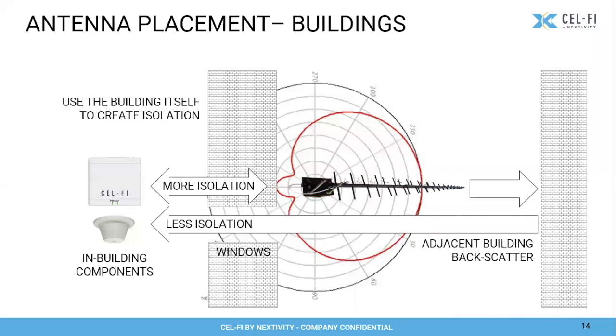But your job is to make sure you have enough isolation that everything is always at max power and you have your maximum footprint from all of your coverage units or service antennas. But then you can run into those cases where there may be a building across the street that is causing a reflection back into the windows below and actually reducing your isolation. In a case like that, you may want to do something with your antenna's direction, right? Point it away from that building or something.